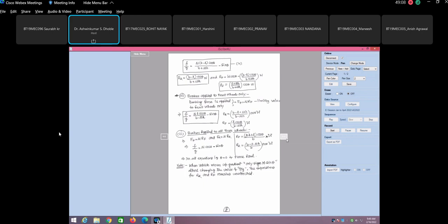There will not be any accident, but we have to analyze this and then make sure that, because in both the cases, if you stop the front wheel, the rear wheel keeps on moving and can transfer the weight. If you only apply the brakes to rear, then front wheel can drag the vehicle. So you have to apply the brakes to the limit that it should not get locked up, and that is the best thing, is to apply the brake to all the four wheels.